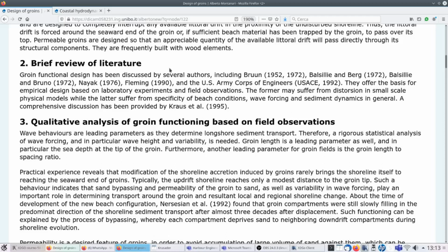In case a detailed assessment is needed, in case we feel that there is too much uncertainty related to the use of empirical formulas with respect to our design project, then we need to make lab experiments with small-scale models. It's very common to make experiments on small-scale models when we have to make coastal engineering design and harbor design.